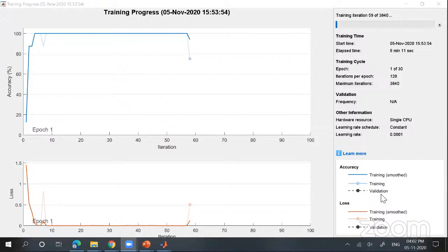Yes, there is a tool for this. You require MATLAB coder products and the specific toolbox or area you're working with. For converting floating point into fixed point, you have a tool called Fixed-Point Converter, which you have to have on your laptop.